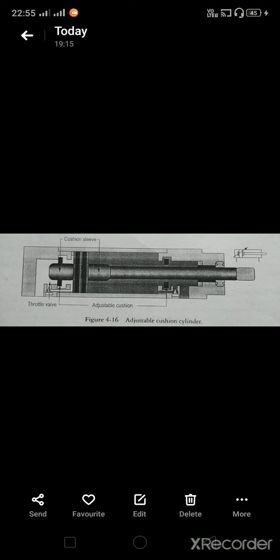The air cushionings are usually designed to function over the final 2 cm of the piston stroke. The cushioning can be adjusted by controlling the throttle valve. In the reverse direction, flow bypasses the throttle valve by means of a check valve within the cushion seals of the cylinder, with a very large force and high acceleration.